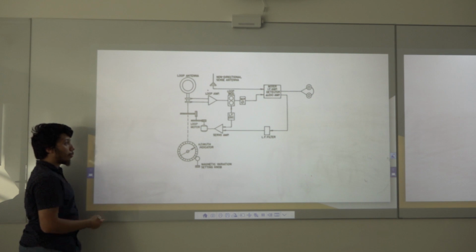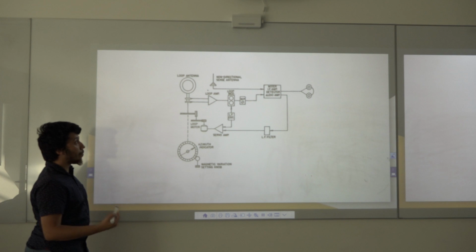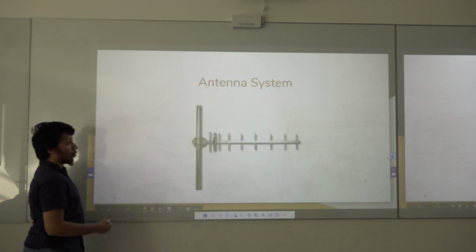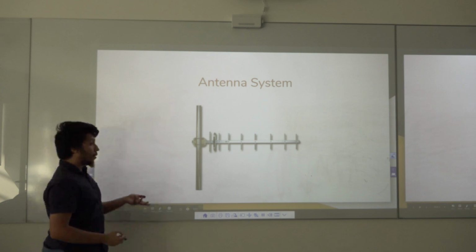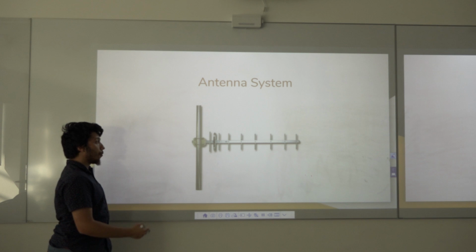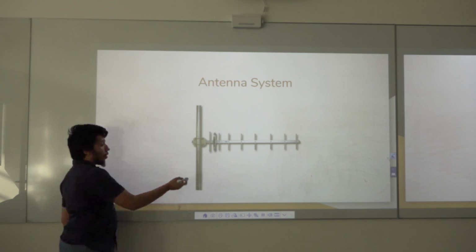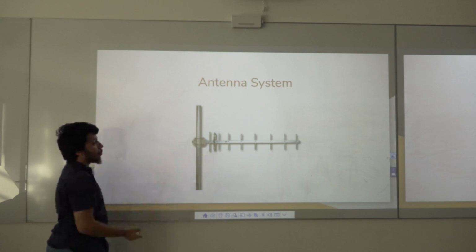Our system takes some inspiration from that, but rather than using a loop antenna, we use a more advanced directional antenna. The system that I imagine will ideally use any directional antenna, but the Yagi antenna is the perfect fit for this system. What I intend to have is a Yagi antenna mounted on the shaft of a motor with a sense antenna for reference.